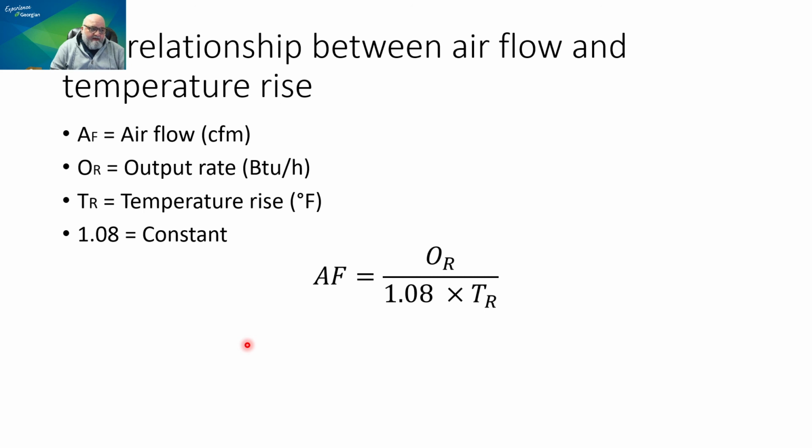So you go there, and the first thing you should suspect is what? Airflow. Why? Because if the filter is dirty, or if the A coil is dirty, there will not be enough airflow. Think about the furnace generating 80,000 BTU, and it requires 2,000 CFM, and you're circulating 1,200 CFM. You don't have enough air to go through the heat exchanger to pick up the generated heat.